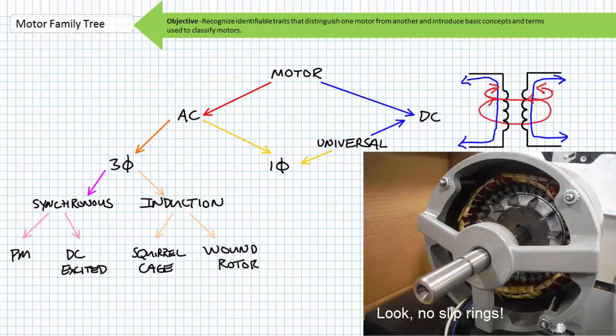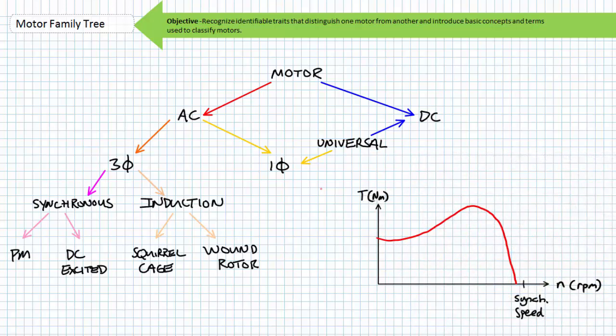Long story short, you don't need any physical connection to the rotor at all for a three-phase AC squirrel cage induction motor. This greatly simplifies maintenance and starting, however, comes at a price. The rotor rotational speed is not nearly as stable as a synchronous motor and varies positively or negatively as the load is removed and applied. What's totally crazy is that the rotor, even unloaded, must necessarily lag behind the synchronous speed of the rotating magnetic field and consume reactive power for the induction process to work at all. We'll go over the details behind this in later lectures.